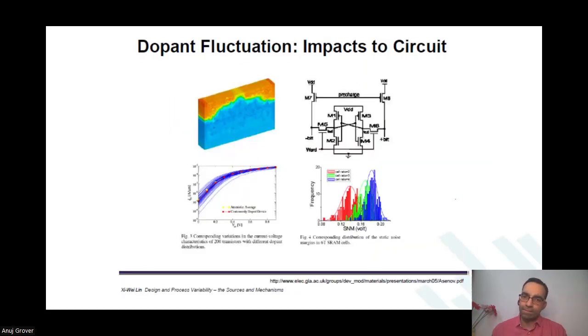Right, I mean, at the worst point of the pass gate, we will do the analysis of all pass gates there, similar kinds of devices. Whatever is needed for that system, at times the lowest VT of the pass gate is what you desire. At other times the highest VT of the pass gate is what you desire. Okay. For SNM analysis, you want low VT on the pass gate. For write time analysis or write margin analysis, you need high VT on the pass gate. Yes sir. So at one time you will use one side of the curve, at another time you will use another side of the curve.